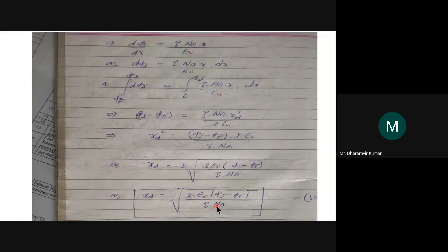Now this doping density may vary. It would vary according to the design, according to the actual doping that is done. But in most cases you will find that the value of Na is somewhere around 10 to the power 16 per centimeter cube. This is a typical value that I am saying. So when you increase the doping density, the depletion thickness decreases.